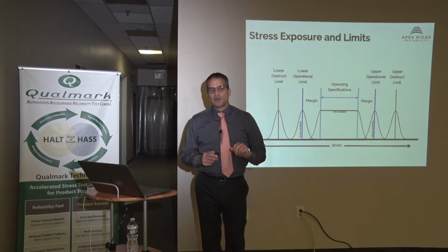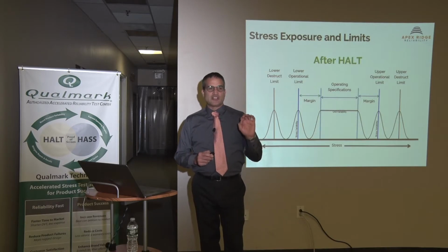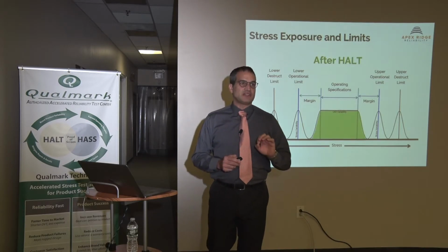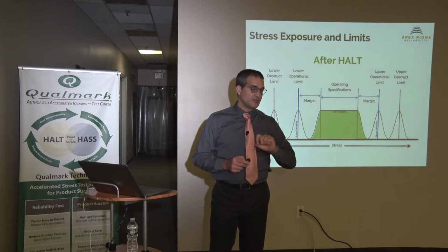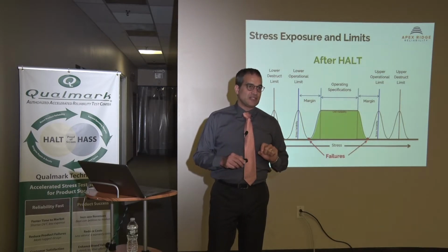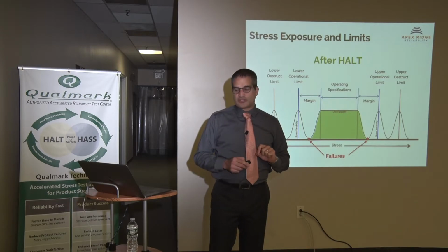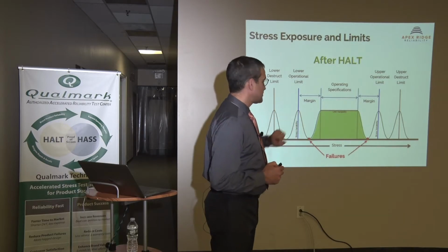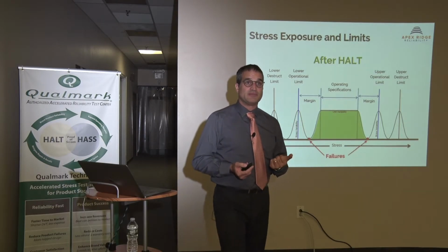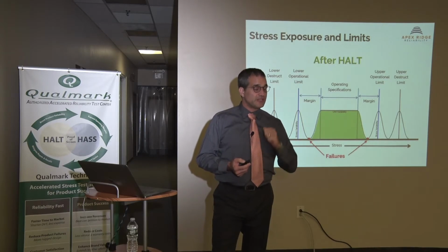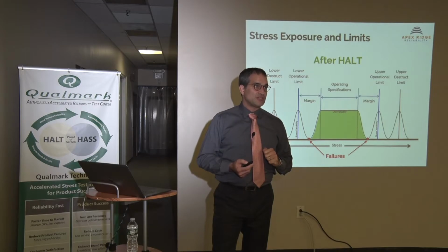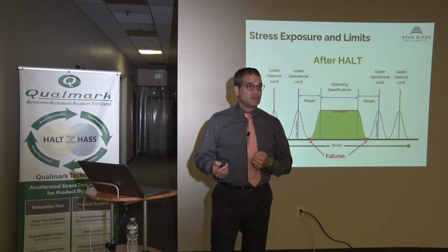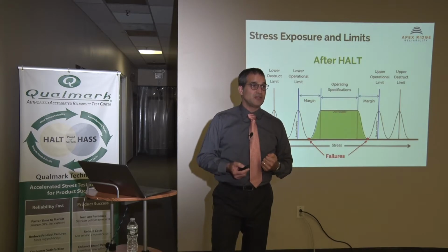Because with HALT, what we look to do is find those failures and change the limits to where the product fails by having quickly discovered what they are through extreme stresses, making design changes that mitigate them. You've now put much larger margins in there. So now your failures are much smaller. And that's the basic principle. We're creating larger margins on stress because we very quickly found out what the failures are, and then we made design changes. And we did that without increasing expense to manufacturing and quality screening or trying to further control the way the product is used.